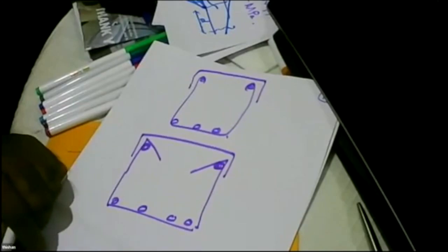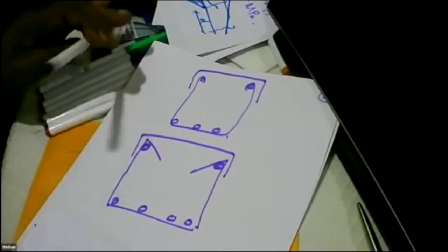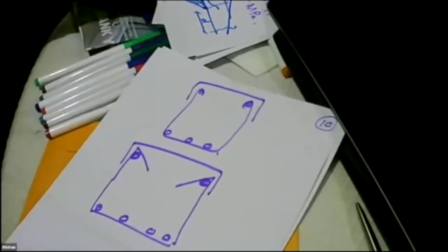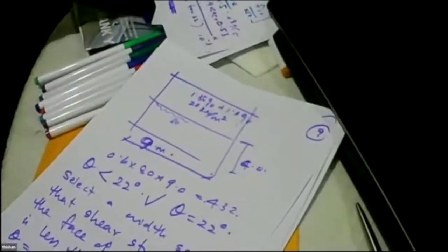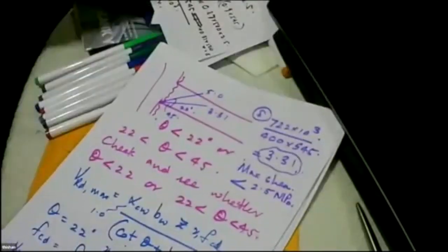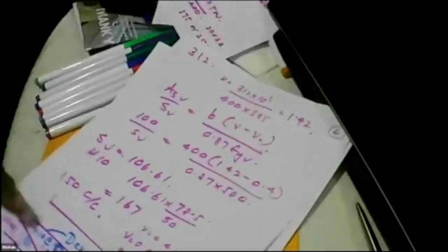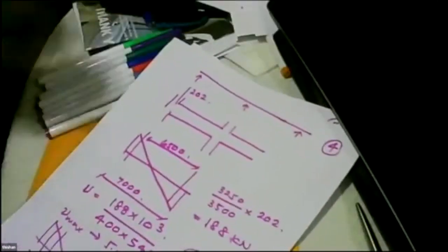Okay. So shear is very simple, but in the code it's very, very complicated. So don't fall into that trap. Never think that shear is difficult. Shear is easy. But you have to avoid all the unnecessary calculations that are given. I don't encourage people to design shear governed designs. It should always be flexure governed designs. So with shear we will be generous, and we can easily be generous. Even locally we can make the beam wider. So don't go for shear governed designs, always go for flexure governed designs.